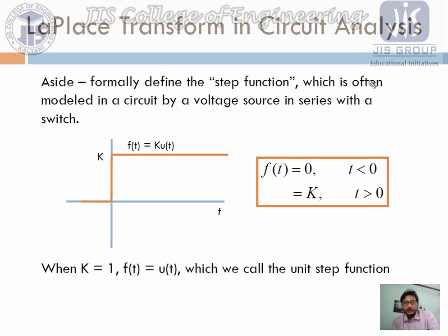So now, before going to the Laplace transformation for electrical circuits, we need to know some basics of different types of signals, right? Step signal, ramp signal, or impulse signal, these types of functions we have to know, because it's very essential. Suppose we have written over here a step function as u of t. Now this step function starts from 0, and it's just like a step. Here the step value is k. It means the signal continues with value k after 0 time.